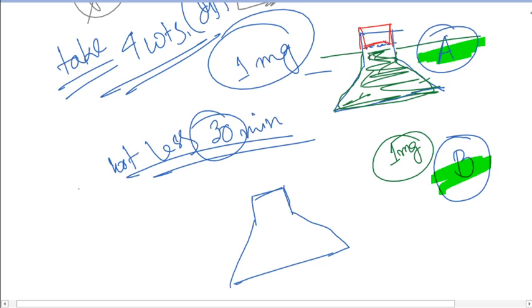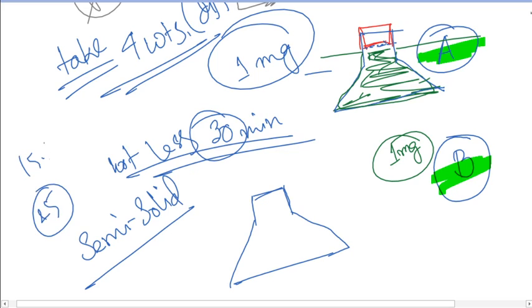And one thing you need to know is why we are calling this semi-solid: because this is viscous. Bitumen at normal temperature is not liquid, not working as liquid as we might expect. Rather, at normal temperature, say 25 degrees centigrade or 15.6 degrees centigrade, it will act as a solid or rubber-like material. So you cannot pour it into a particular shape like a liquid.